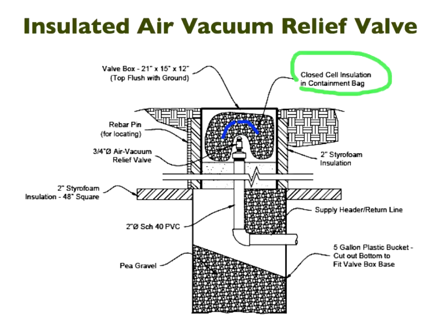Now this is wrapped around so that it is insulated. There's styrofoam insulation around the casing here. Okay, and here they've included a rebar pin so that when it's under snow, when the snow is 4 foot up here, if you do need to find it, you can locate it with the steel pin. Okay, and this will go down now.